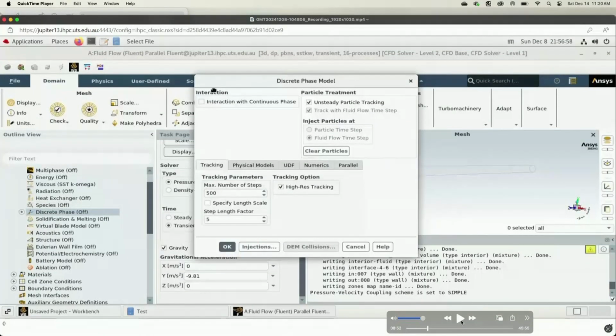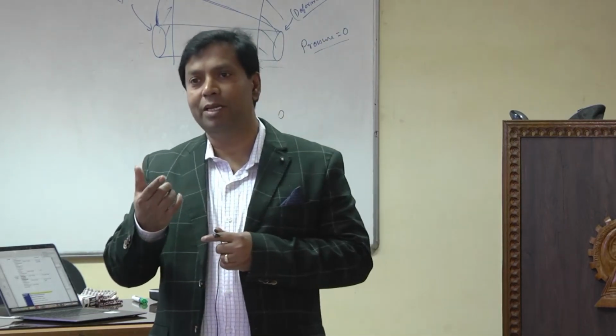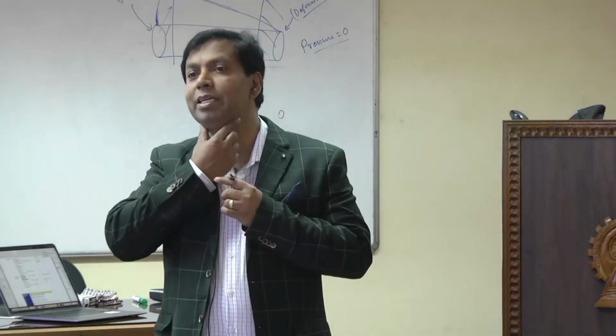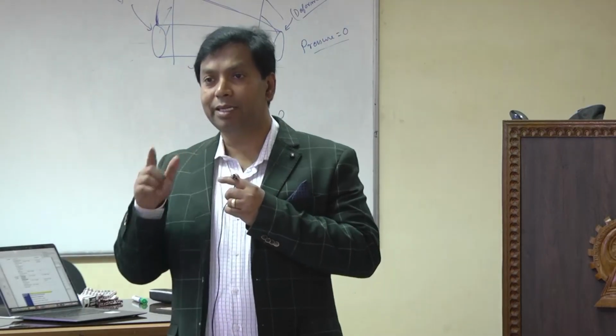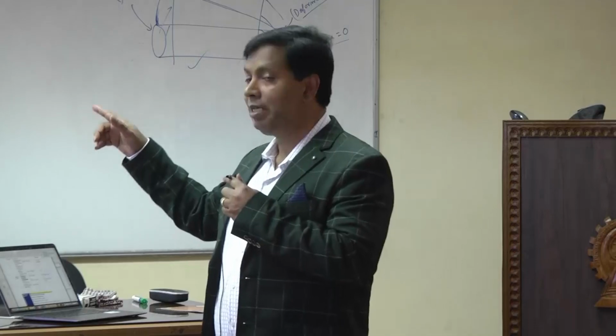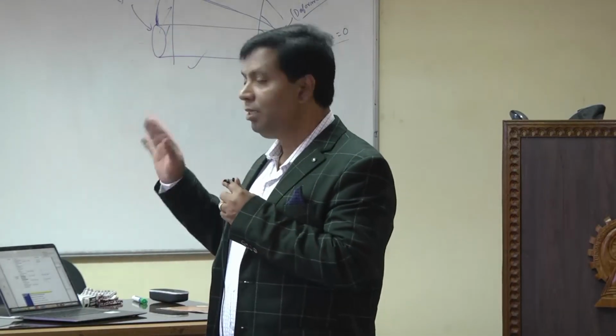In the whole lung there is turbulence. Even though for small airways the Reynolds number is small, around 100, you can experience some turbulence near the larynx. That's the reason they just use the turbulent model. You can see most of my published papers use the turbulent model.